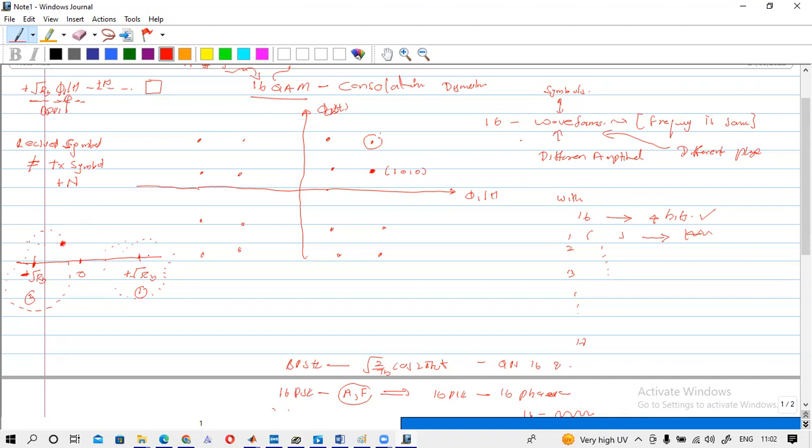But for this kind of modulation, these are somewhat symmetrical. So for this kind of symmetrical modulation scheme, we can just take a decision boundary by looking at the position of the two symbols. You can see that here you have 0, and here you have one symbol at some distance from 0, and here you have one symbol at the same distance from 0.